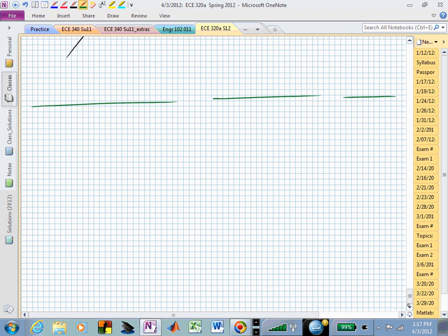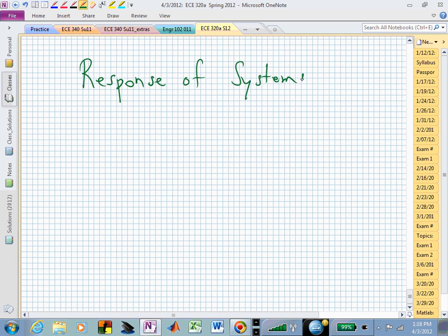That's now some ways of finding the transfer function, H of S, capital H of S. And if you needed to do convolution, you could inverse Laplace transform those capital H's into lowercase h of t's to find the impulse functions. You now could then convolve waveforms to find your output response, or you could multiply their transforms to get the response of these particular systems.